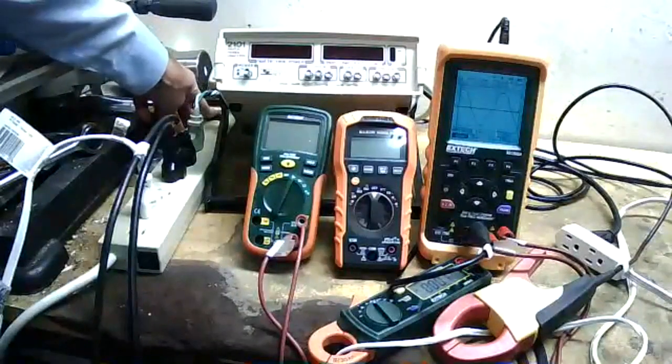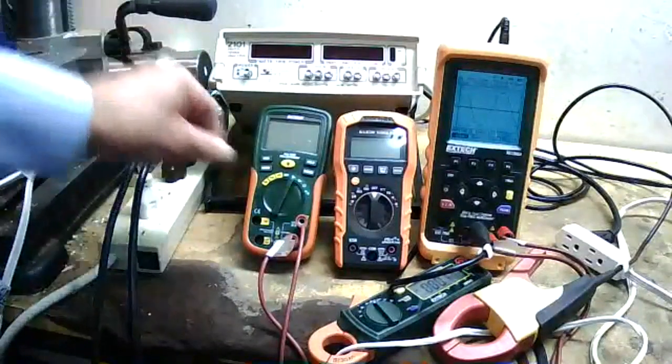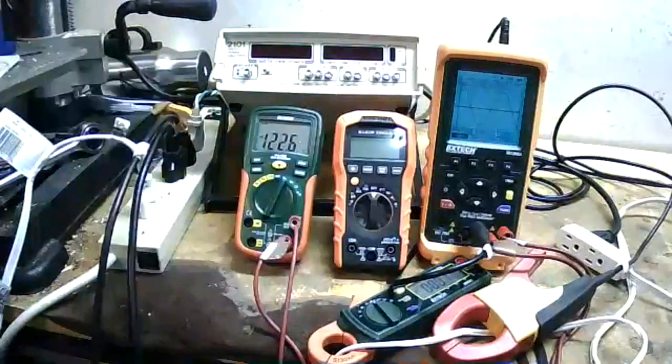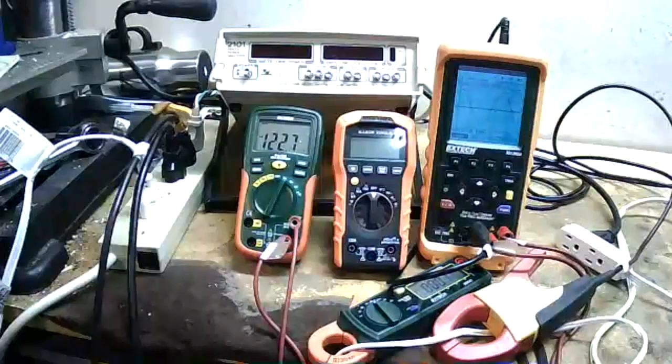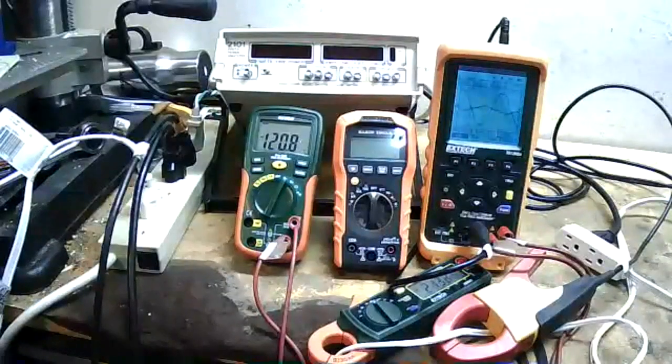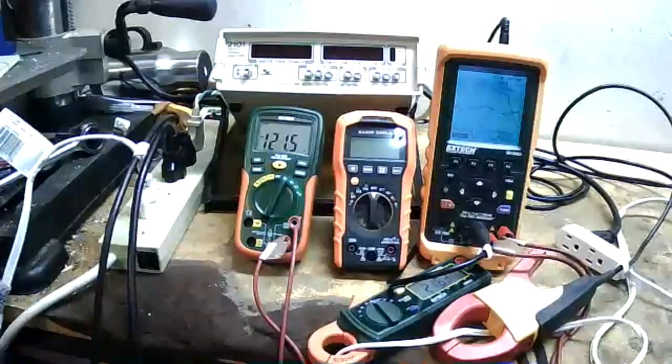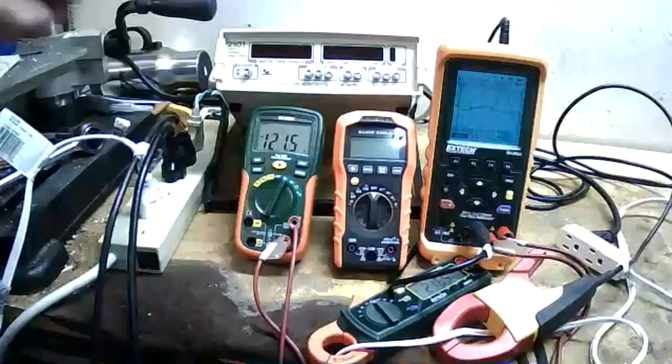I will turn the power to the circuit back on. Turn the meter back on, but what we're really interested in is that oscilloscope. Now, we can see the voltage and the current waveforms, and what I am seeing is that they are almost 180 degrees out of phase, which means I connected the current clamp in reverse.